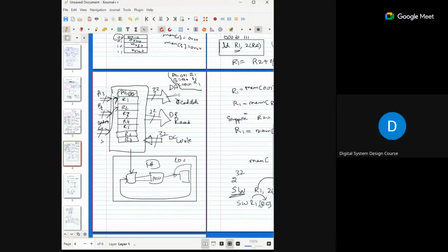Here I'm reading the data at the address of R1, which is 10, and data line B is pointing to the R2 address, which has the value 20. With this data, I'm passing these two values to my arithmetic logic unit, doing some process, and returning that data back to the register file. That data is FF. This is the write address, the write data, and these are all my read data. So after processing, we are writing FF to register R1?